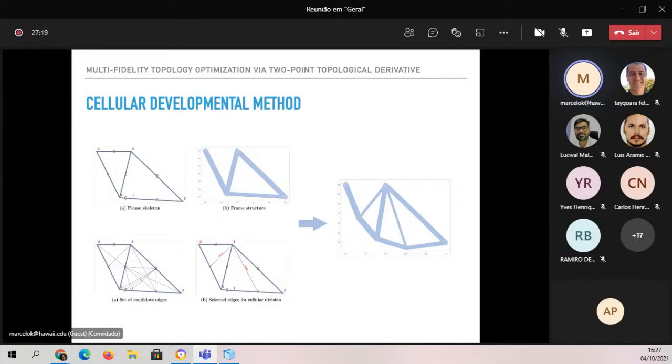So if you think about it in this process of cellular division, I start with that blue on the top right, and then after cellular division, I end, with the cellular dynamics and the shape optimization, with the one on the middle right. And you see that when you put those red bars, of course, it creates bending on those bars that are connected to, and so the shape optimization, as you see, is a shape optimization to relieve the bending in those bars.